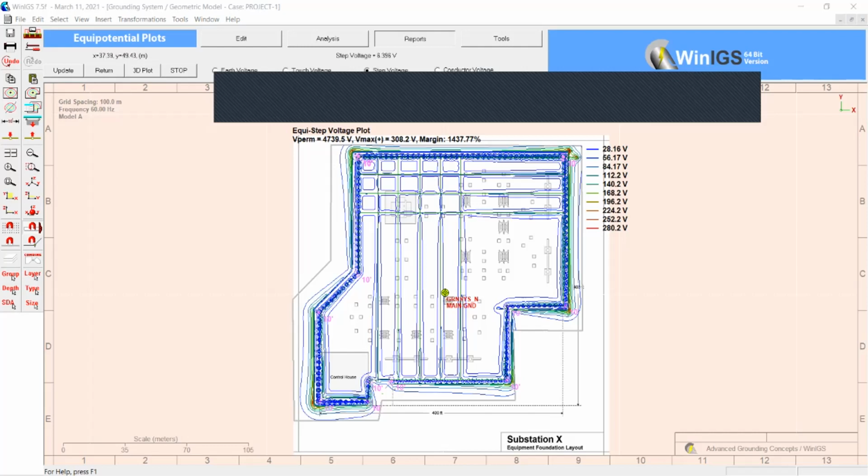So this is the way you have to analyze. But if you see that your ground potential rise is more than 5 kV, and touch and step potentials are beyond the allowable level, definitely you have to modify your model. First try not to change the grounding conductor or anything; just modify the soil resistivity, top and bottom layer and thickness, within the tolerance you will have.